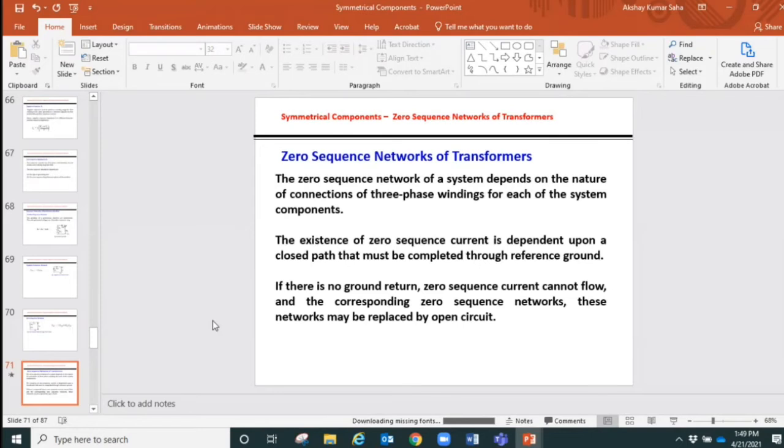Now, when we connect the load on the secondary side of the transformer, then secondary current I2 will start flowing, and because of that secondary current I2, there will be an increase in primary current. That primary current will have another component, which can be called the reflected component of the secondary current in the primary, and it will depend on the ratio of N1 and N2 or V1 to V2, whatever you call it, transformation ratio or turns ratio.